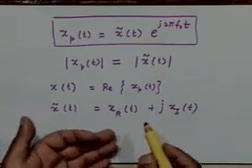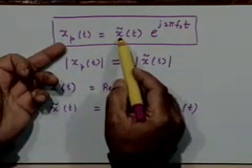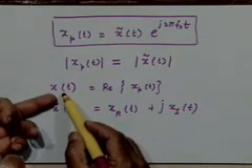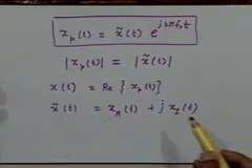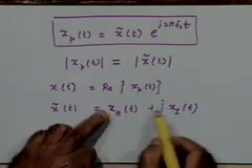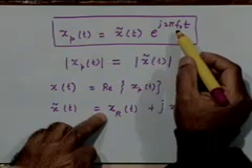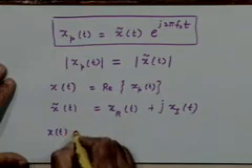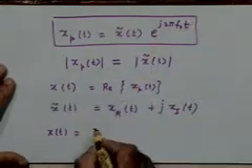And just like I have a representation of x_p(t) in terms of x tilde t, what I would like to find out is whether there is a corresponding representation of the original bandpass signal in terms of these components. It's very simple. All you have to do is substitute for x_p(t) into e to the power j2 pi f naught t and take the real part of that. So what will you get? We will get x of t. What will be the real part of this multiplied with e to the power j2 pi f naught t?